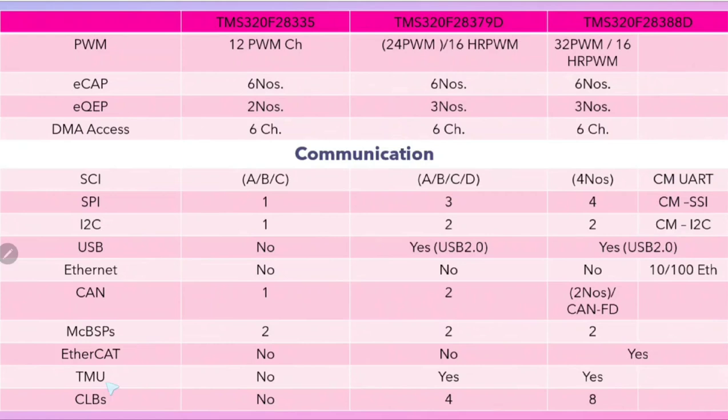Now if you are looking at the trigonometric math units, the F28335 does not support the trigonometric math units, and the F28379D and F28388D microcontrollers support the trigonometric math units, and they also support the CLB and control law accelerator blocks.